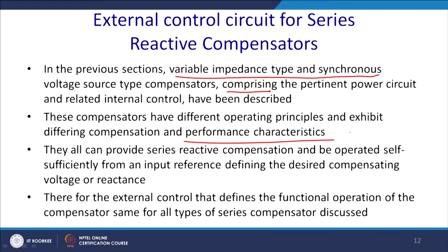So, they all can provide series reactive compensation, whether it is the impedance method or the voltage controlled method where you are injecting a voltage source. Both can control the series reactive power compensation and be operated self sufficiently with input reference defining the desired compensating voltage and reactance.